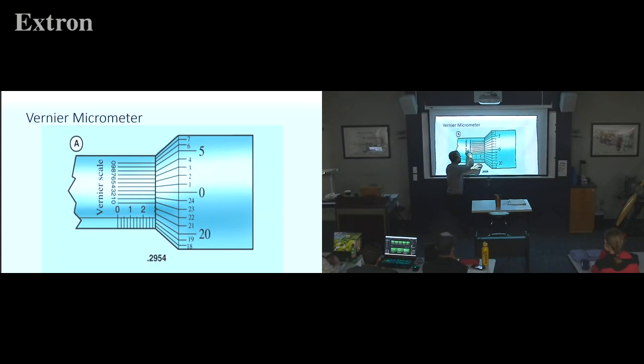So then you bring that 4 down here. Don't bring this one, you're already done with that scale. Once you've got the 3 digits, you're going to use this scale for the fourth. When you've got the thousands, you walk up the ladder until a line lines up, and that line, you put in the 10,000s.